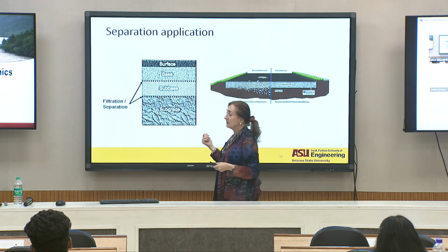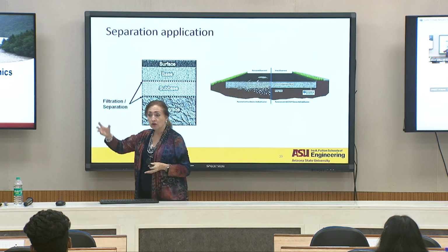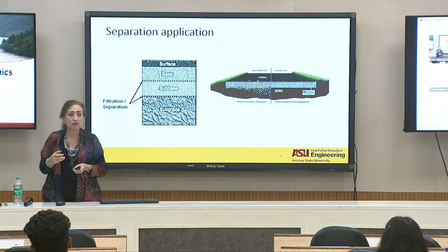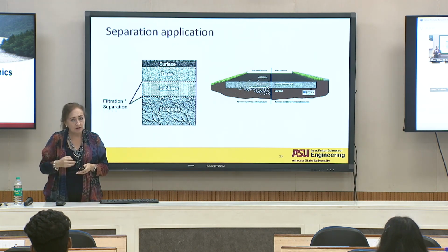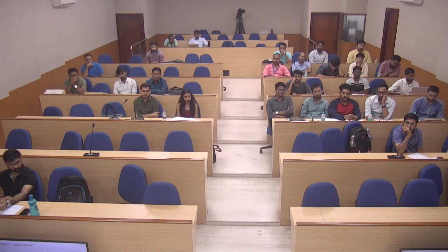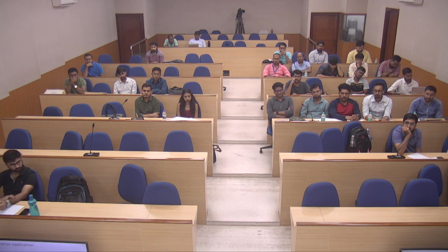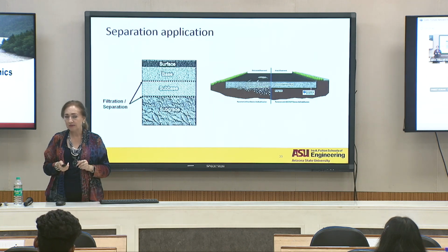So we did a lot of testing on resilient modulus and the moisture accumulation and suction accumulation of those fines, and it's a tremendous problem if you have 3-4% more fines in those granular-based materials. So you want to avoid fines in your granular-based materials.